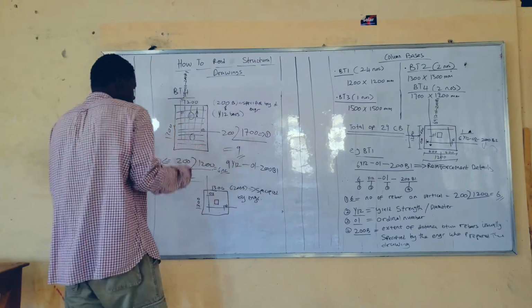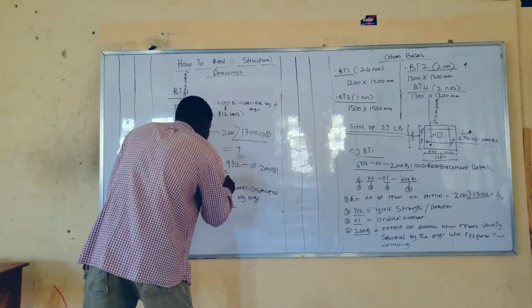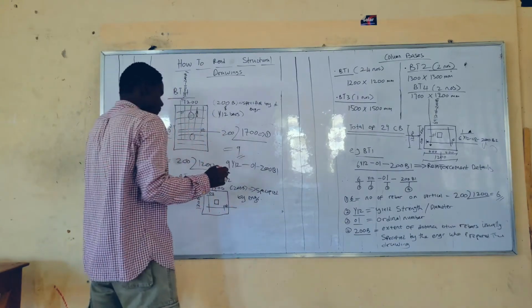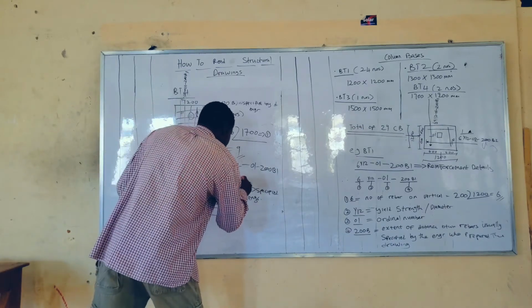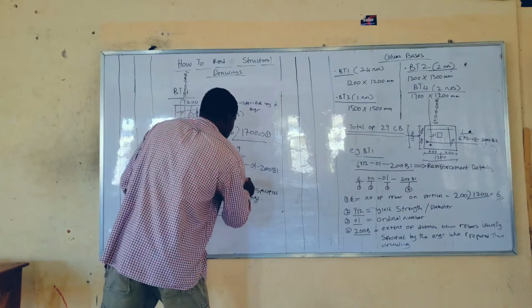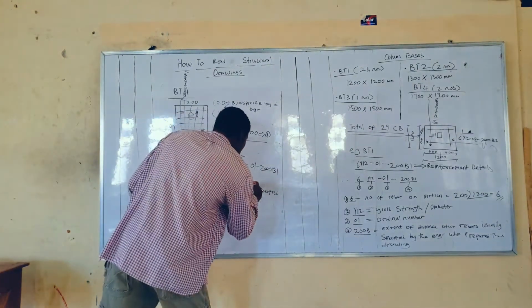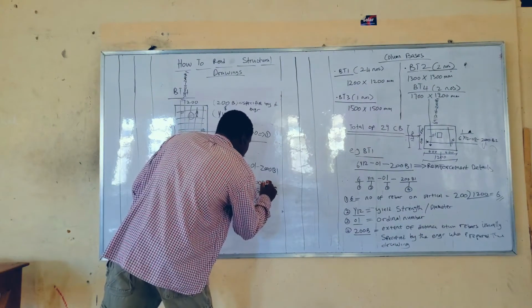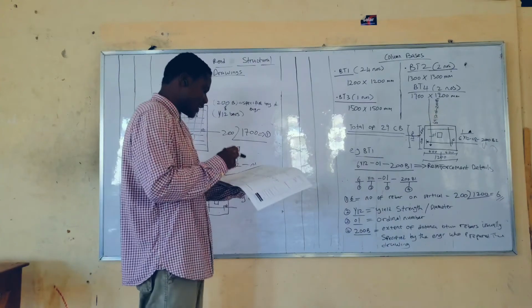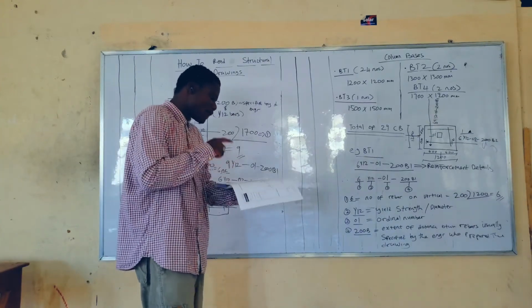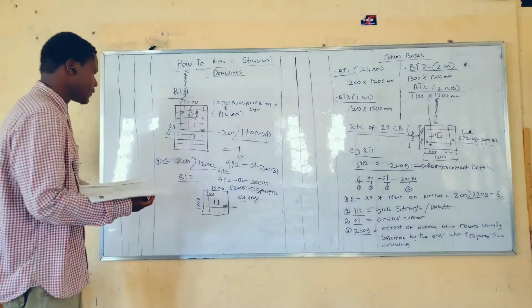So that's 6 what? Y12 bars for number 2, which is 02. The space between them is what? 200 millimeter. 200 B2. And if you look at the drawing, that's exactly what's there. Look at BT4, base type 4, 2 numbers. That's how to read your column bases.